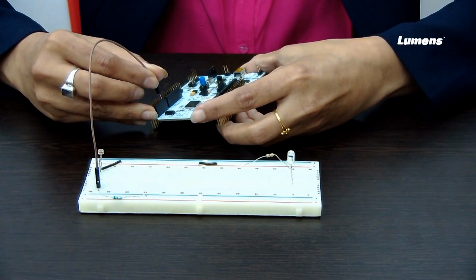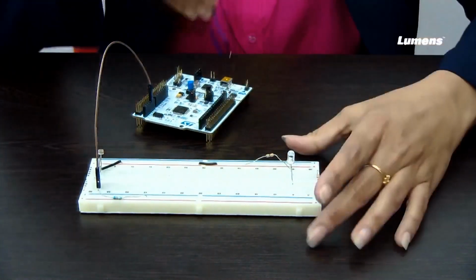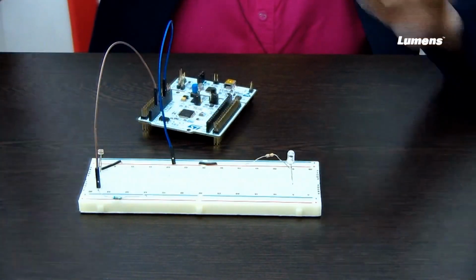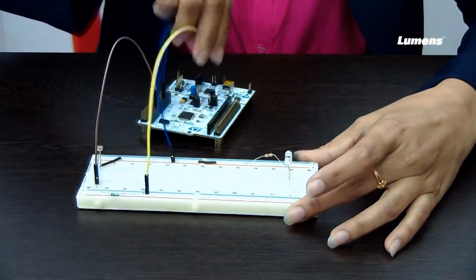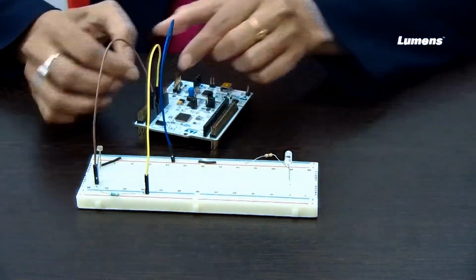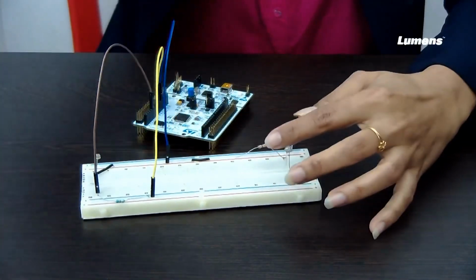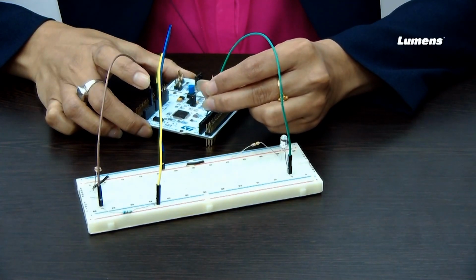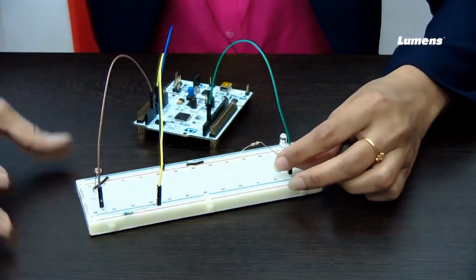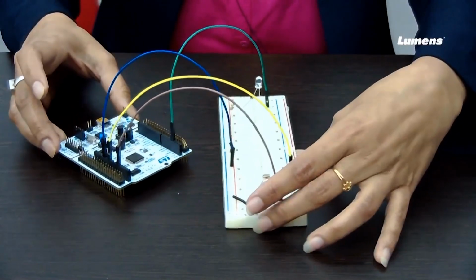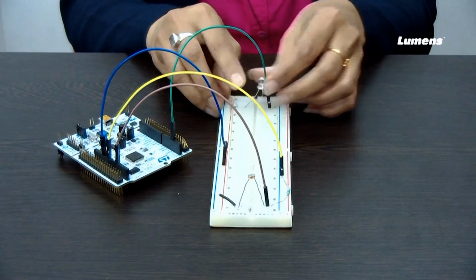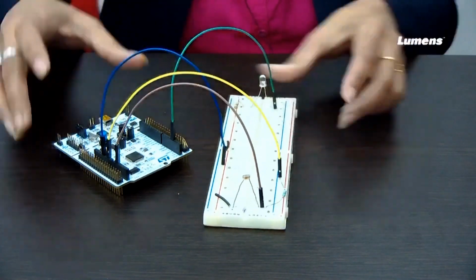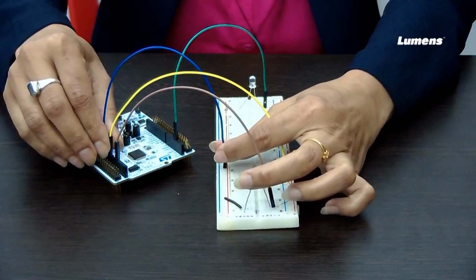So, this, as I said, will be connected to A1. This point is connected to VCC. And this point will be connected to your ground. Okay. And from this point, that is the cathode of this LED, will be connected to the PWM D3 port. Okay. So, this is all about the connection we need to do when we do this experiment using LDR intensity, changing the intensity of the light depending on the ambient light. Okay. So, now I will dump the code that I have already discussed with you once the connection is all right.